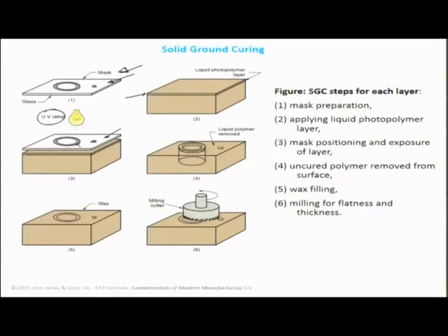In this particular case, if we use a positive resist, you can think of the positive photopolymer as being debonded as light falls over it. So wherever the light is falling, the photopolymer would be dissolvable, so it can be dissolved away, and wherever the light is not falling, there is going to be a resultant structure or a 3D feature in place.